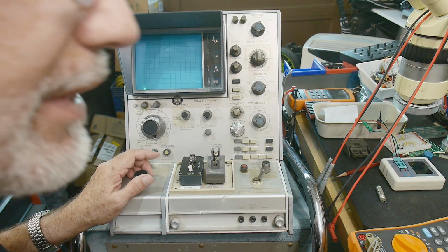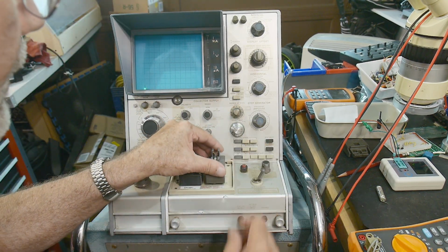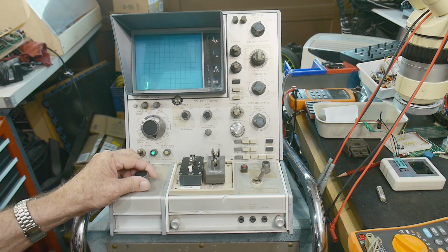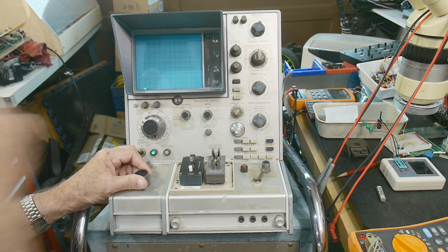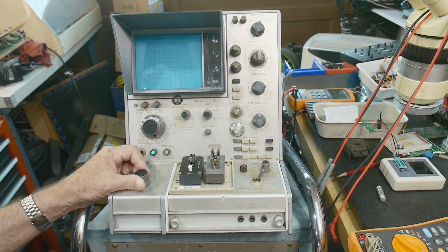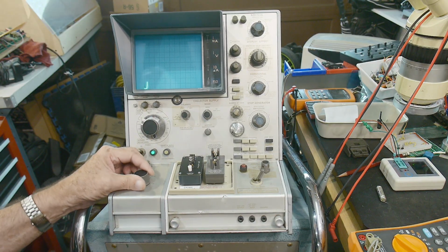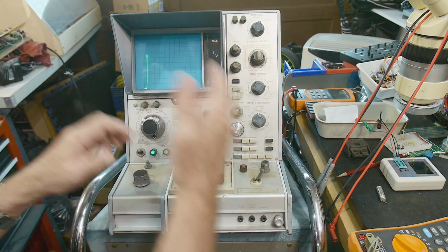So we can put something in like a diode. Okay, put it in the right way around. It helps. Okay, there we go. What just happened? I'm at 1 volt per division, and suddenly it turns on. Well, that's because a diode, after about 0.7 volts, starts to turn on. It starts to conduct.